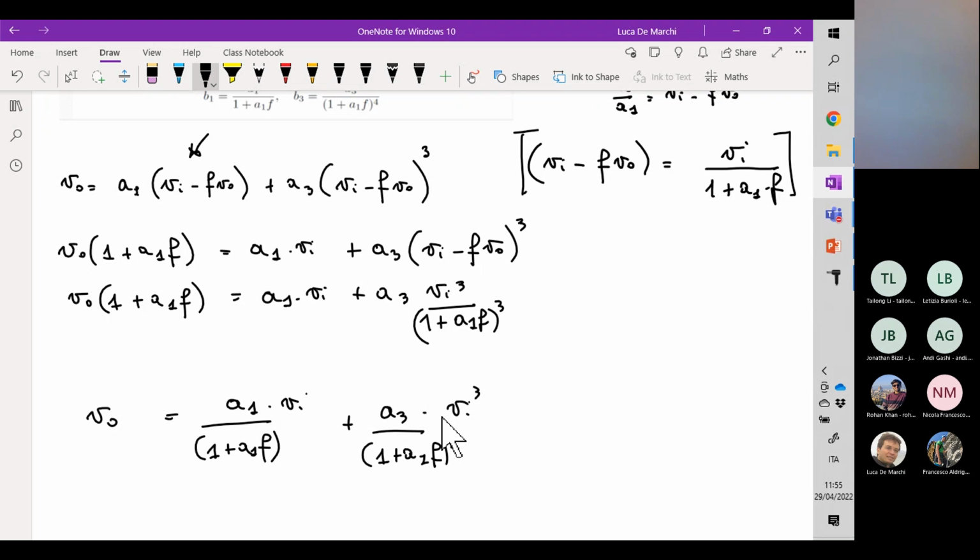In this case, again, we want the actual output to be as close as possible to the gain generated at this point. So this actually would be A times VI times RL over RL plus Z out. Okay, so it is important to have a very small Z out. We want this quantity to be very small because we don't want this ratio to be far from the unity.